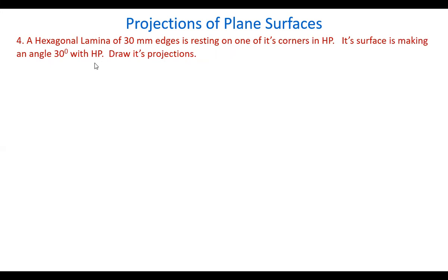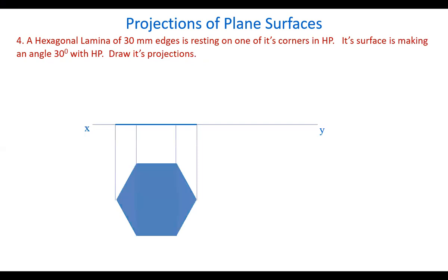So first take the plane either in HP or parallel to HP because of the surface inclination. Second, it is resting on something on the horizontal plane. That's why take the plane, entire plane in the horizontal plane itself, like this. So we take the plane on the horizontal plane, that is, in the horizontal plane means automatically you can even call it as parallel to HP. Now,